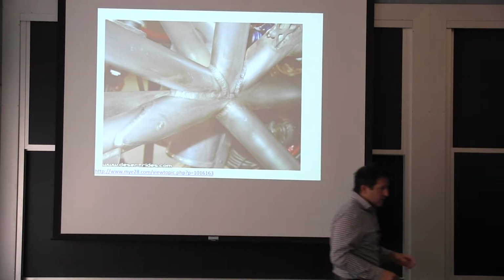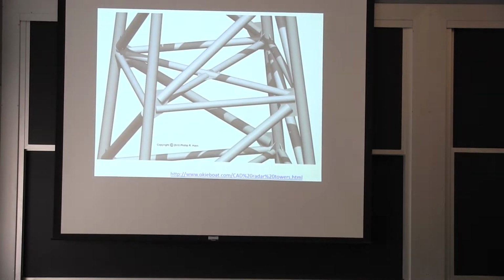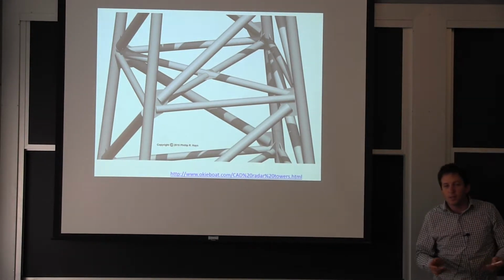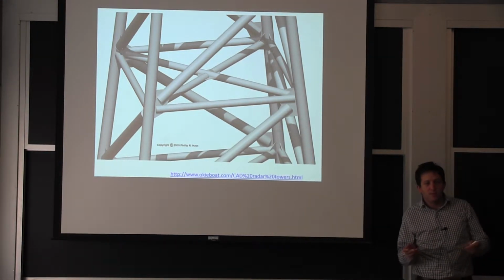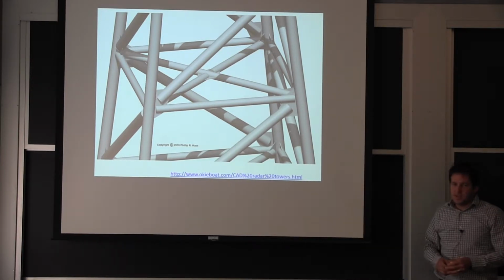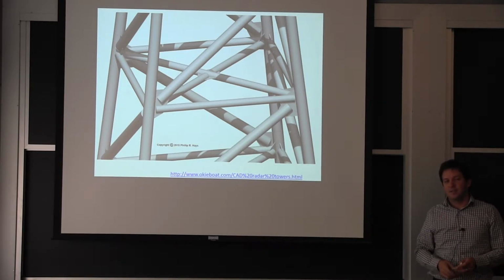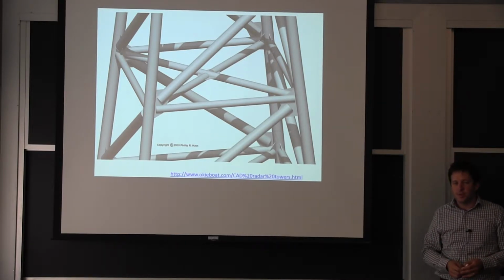So that's why a lot of times we end up designing tubes, and you'll see both if you travel across the country in the airports. Sometimes you come in an aluminum structure, you see a steel structure, and you'll see both. You'll see the case where it's welded all around. It looks nice. It's good for water penetration, but it gives you stresses in the welds.